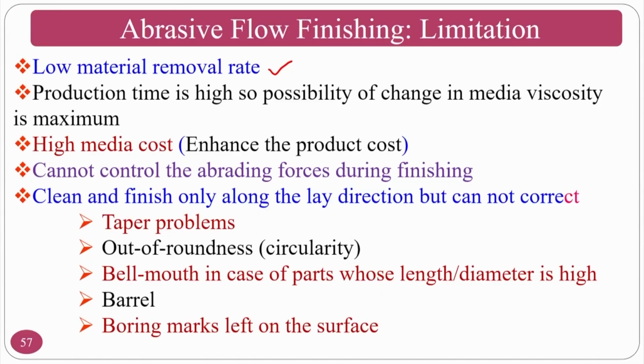If you are looking for machining or material removal, then the abrasive flow finishing process is not the right process. If you are looking for finishing applications, getting a nano surface finish, then this process is good. That means a low material removal rate. Production time is high, so the possibility of change in medium viscosity will be maximum.